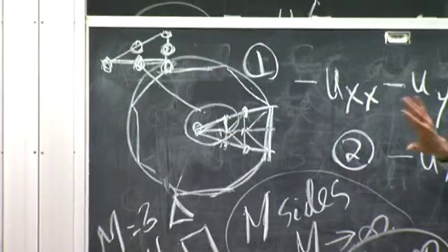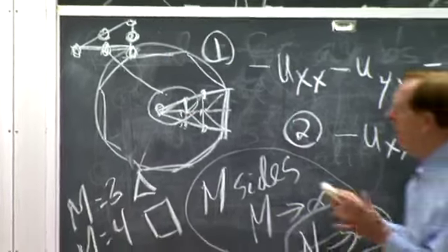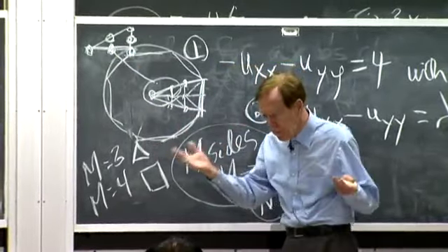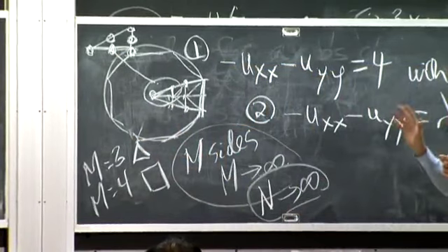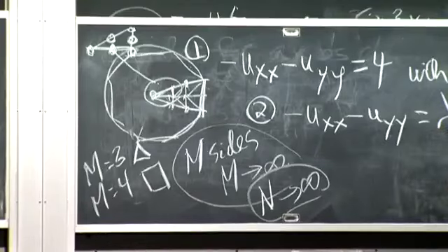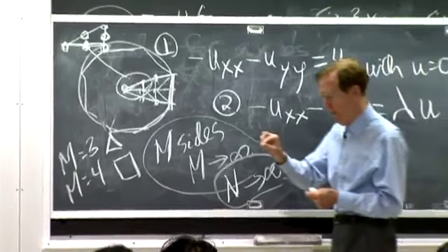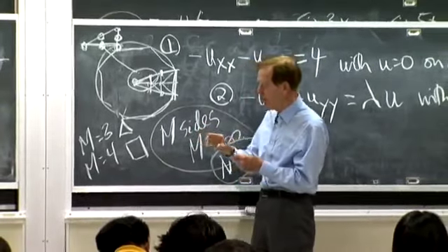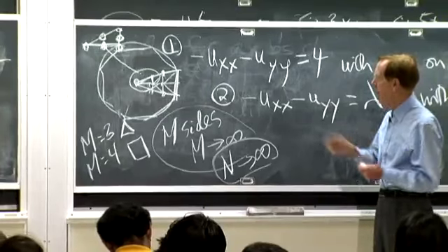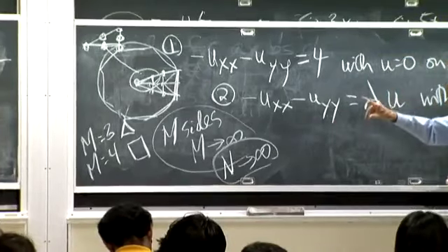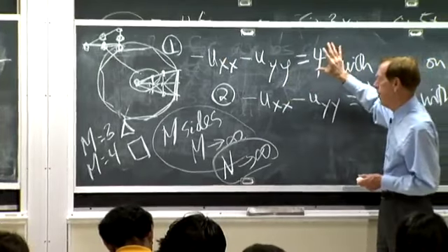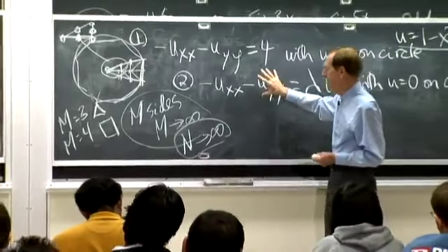The trial functions phi, which are 1 at a typical mesh point and 0 at all the others, are computable, but we're up to second degree, so it's a little harder. Then the first derivatives, which come into the integrations, are linear and not constant. So a little bit harder. But finite elements, linear or quadratic or higher, could be used for this problem, as we know.